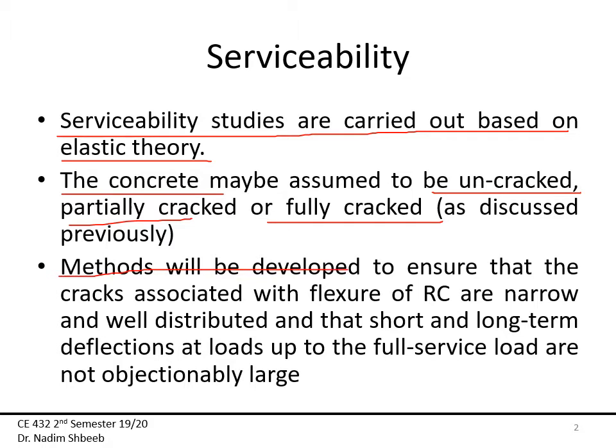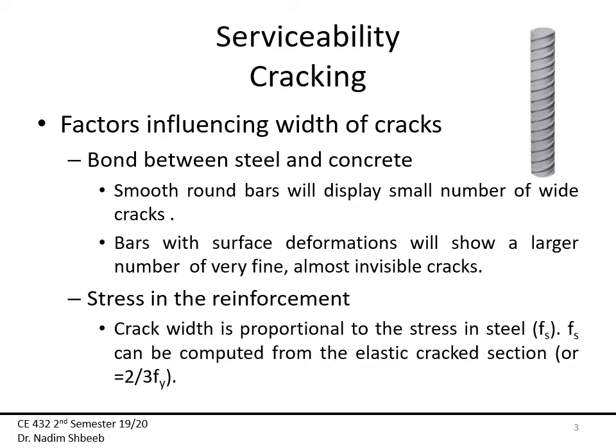The methods that will be developed will ensure that the cracks associated with flexure of reinforced concrete are narrow and well distributed, and the short and long-term deflections at loads up to the full service load are not objectionably large. Again, it's all about the control, not the elimination of both cracks and the deflection. Now, we're going to start with crack, and discuss the factors that influence the width of the crack.